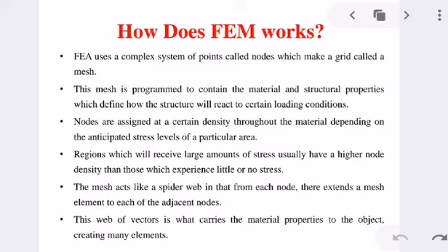The nodes are assigned at a certain density throughout the material depending on the anticipated stress levels of a particular area. Regions which receive a large amount of stress usually have higher node density, and the mesh acts like a spider web, and this web of vectors is what carries the material properties to the object, creating many elements.